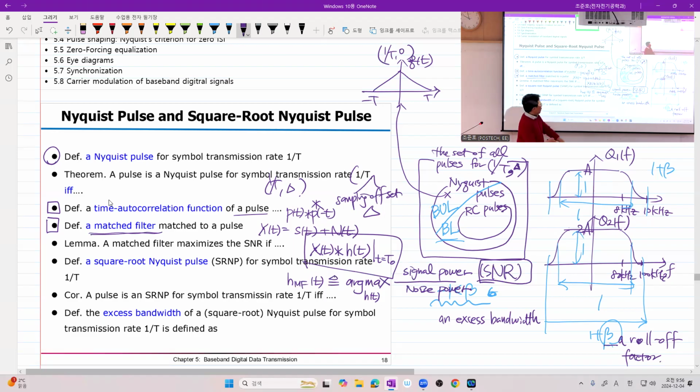so it's okay. The problem is that this signal to noise ratio has the numerator proportional to the scale of this one, and noise power also proportional. So actually, if you find the solution, you have infinitely many solutions. However, they are all scaled versions of a single, single non-zero pulse. So using some kind of equivalence relation, we may say that the matched filter is uniquely determined. Got it? Anyway, an interesting thing is this one.